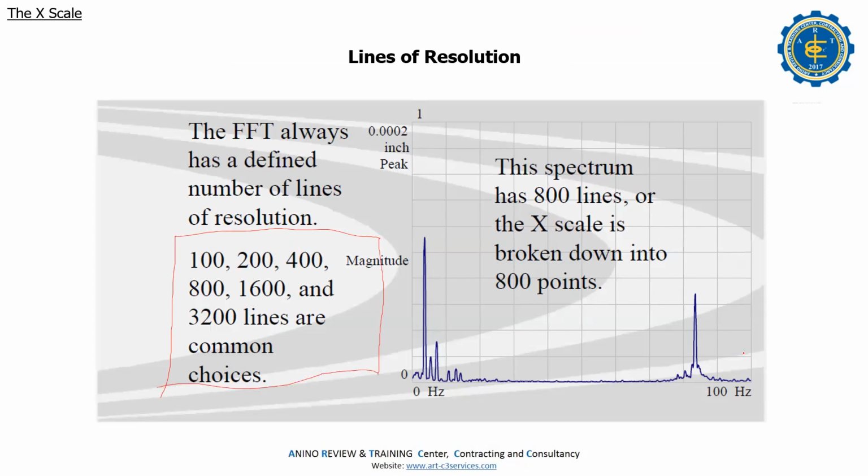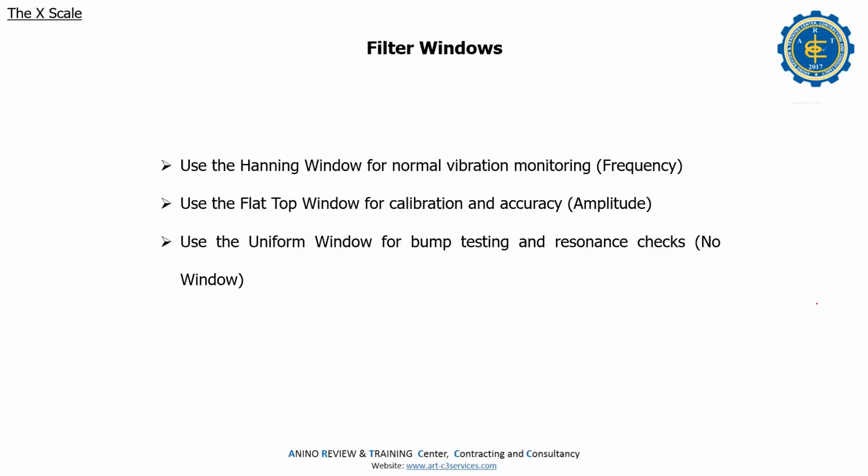How much is your frequency here? You go 1,000? How much? Or you go 2,000? We go more than 3,000? We go 10,000? Okay. Because we have low frequency, medium frequency, and high frequency. So you have to make sure of the bearing. You can monitor the bearing because bearing is in the high frequencies. So filter.